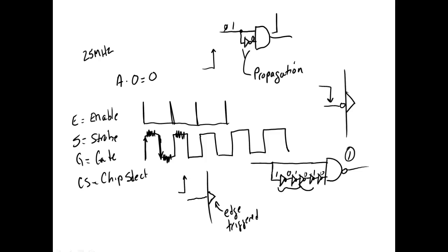And what is the propagation delay? Yeah, it's how long it takes the output to respond to a change in input. That's how long it propagates. The basic gates are not too bad. A standard gate is like 10 nanoseconds. An LS series is like 9 nanoseconds. An S series is like 3 nanoseconds. But we've got some of these that can really scream.